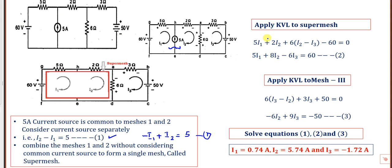While applying KVL for the super mesh, start from the 5 ohms. It is 5 into I1, because only one current is flowing, as it is at the edge. In the 2 ohms, only I2, because it is also at the edge: 2 into I2. While writing KVL, what are the original currents? In the 5 ohms, only I1; in the 2 ohms, I2.